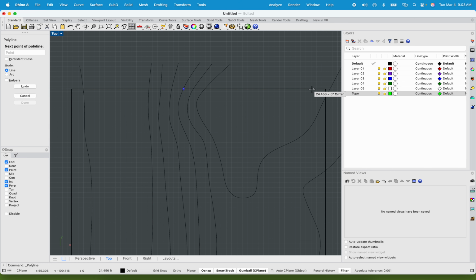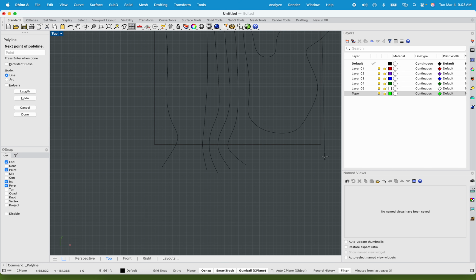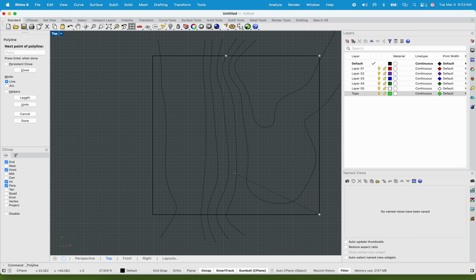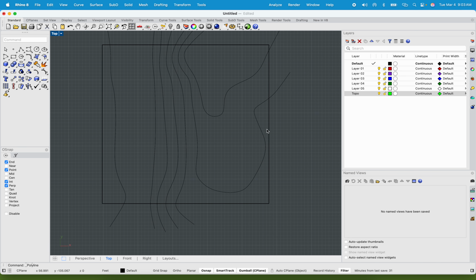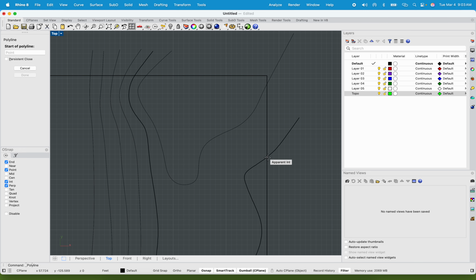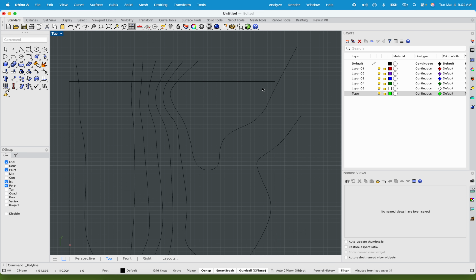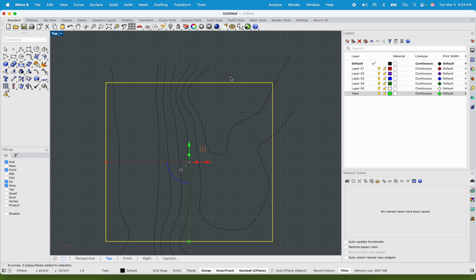Take that line, click, basically using my edge and referring back to the original line, right? So, pop, sweet. And we got that piece. This piece should be actually fairly easy. There's my intersection, intersection, and intersection. And last but not least was one that we drew previously, that piece, and that intersection. So do make sure that you have the intersections enabled. So we'll take all those pieces and we'll trim them.